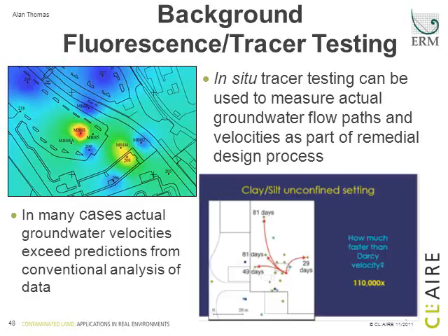And I think the slide in the bottom right hand corner there is from a real site where a tracer was added in a particular part of the site, and you can see the varying particle pathways and travel times from that point of injection, and obviously in addition the rate of movement compared to the Darcy calculation.